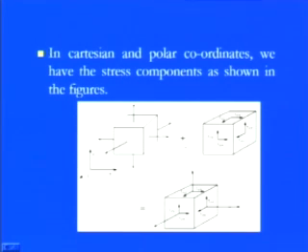And if I add the shear stress components, so here, if we are working in this domain, which is my z domain, what are the shear stress components in the z domain? Tau zy, because the y direction is on top, so tau zy, because z is the area where the cutting plane is, the normal to the cutting plane. So this is my tau zy in the vertical, and this is in the horizontal, tau zx.